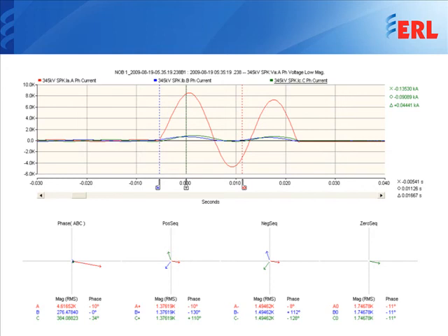For this case, we have about 1300 amps on positive sequence, about 1400 amps for negative sequence, and 1700 amps for the zero sequence. And for my A phase vector, we see that it has increased significantly. So this is clearly an A to ground fault.